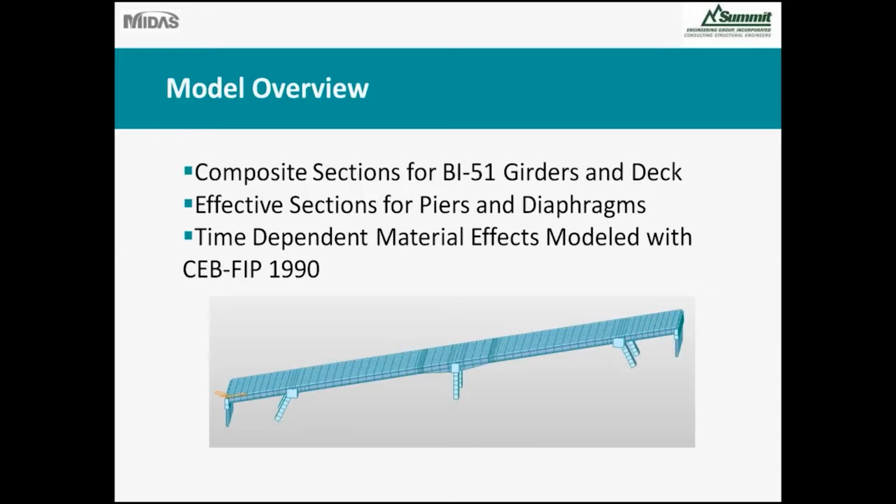The reason we did this was because the post-cracking behavior of the piers allowed them to be a little bit more flexible, and the bent caps were experiencing high degrees of compatibility torsion, which did not affect the equilibrium of the structure, however, attracted a lot of torsion with any kind of differential loading. So I did some research and was able to reduce the torsional constant of these sections, allowing for more efficient reinforcement based on the true behavior of the structure.